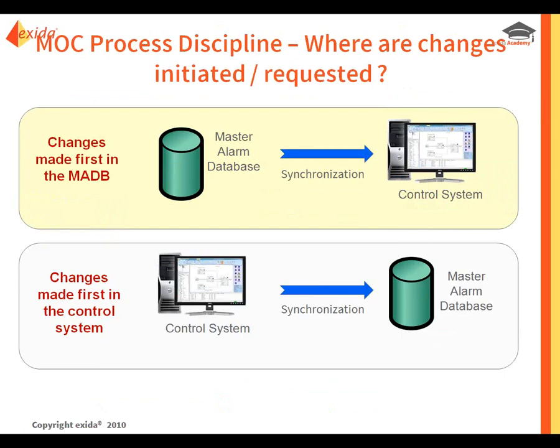Now let's talk about your management of change process and integrating the master alarm database into it. Given that what we're talking about is the master alarm database, the idea is that it would be the single repository for your alarm settings and configuration and would dictate to everything else what those settings should be. So one might assume that any potential changes to an alarm setting, once they've gone through management of change and been approved, should be implemented in the master alarm database first and then pushed into the control system, or implemented in the control system next.